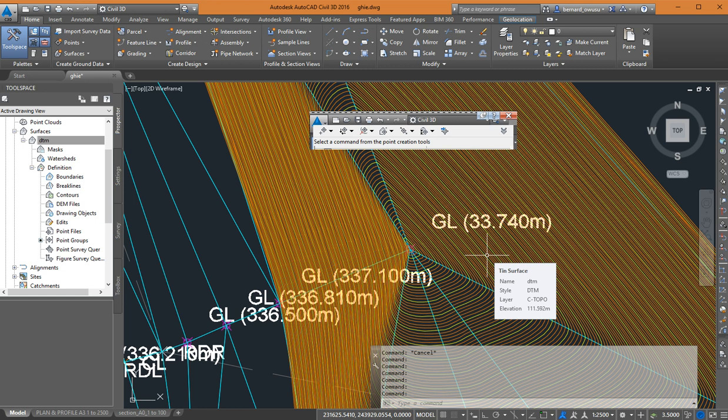Please, are you okay? But at a point it rises up, but I think the minimum, we can assume, let's say the minimum elevation is 200, for example. So we are going to tell it that any value that it sees below 200 meters, it should forget, it should not use it. Though the point is there, we have not edited the point, you will see the point, but it should not use that point in building the surface. Please, are we okay? Any question?